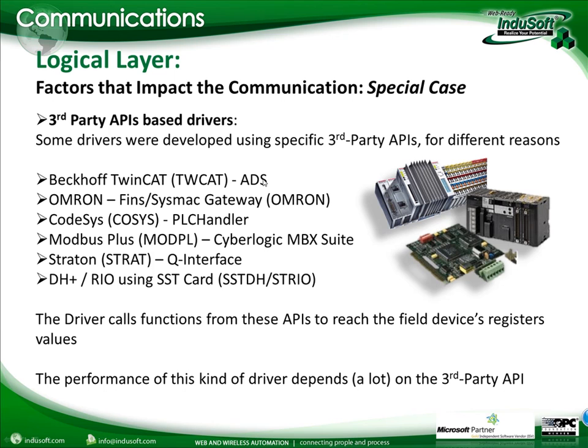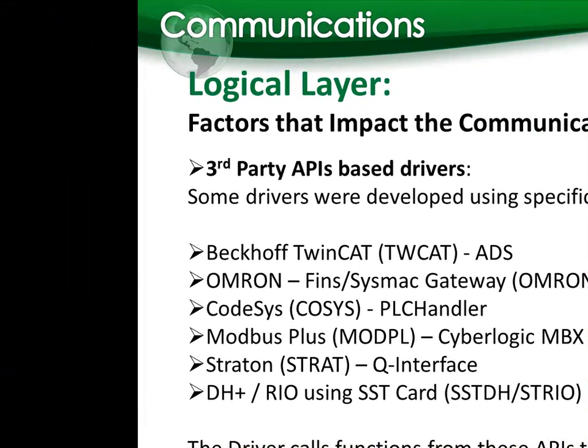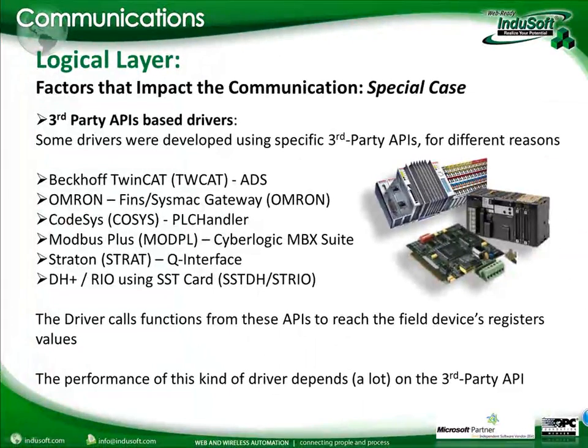It doesn't matter if it's a soft PLC running on your PC, or one of their Windows CE devices, or proprietary hardware like the BC9000, BX9000. The ADS from Beckhoff is the one that's going to go to the PLC, and our TwinCAT driver is going to go and talk to the ADS. So the driver goes to the ADS, which goes to the PLC.